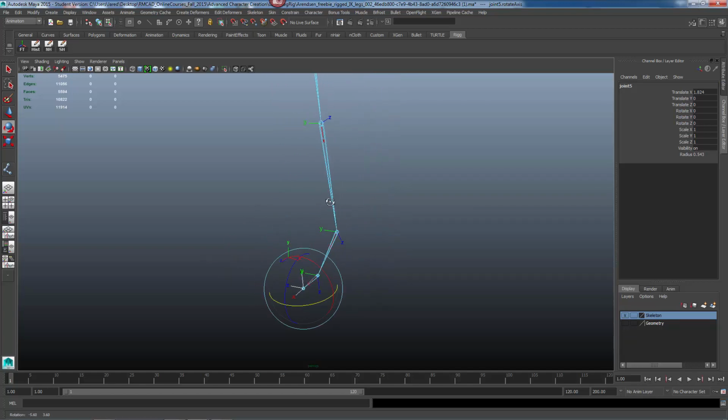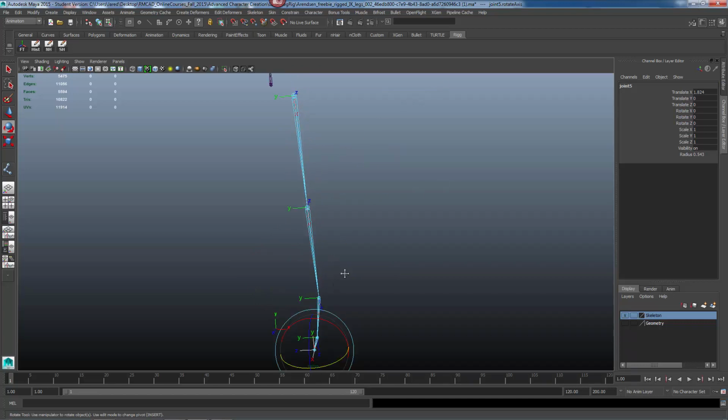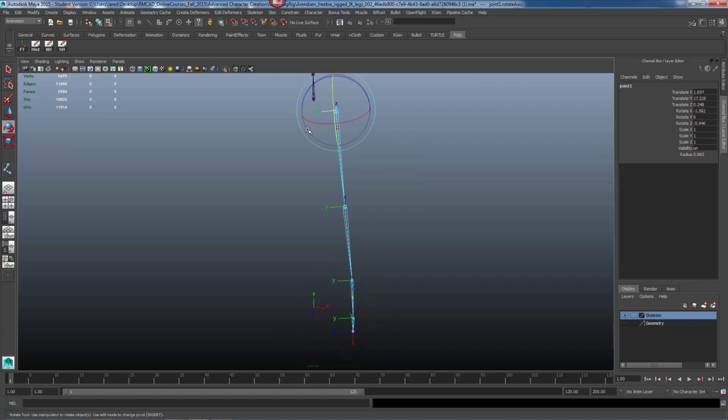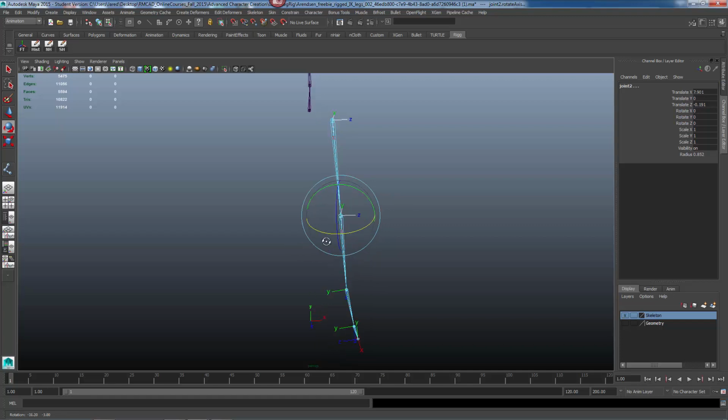I'm going to take my Z's, and I want all my Z's pointing away from the body in this case. So anything vertical, like a leg or the spine, the Z should be pointing to the left away from the body. To show you, I can select multiple ones as well. So select that one, shift select this one, and the one at the bottom is different. So I'll take these two. I'll use the same hotkey, the J key, and click and drag those to snap them like that.